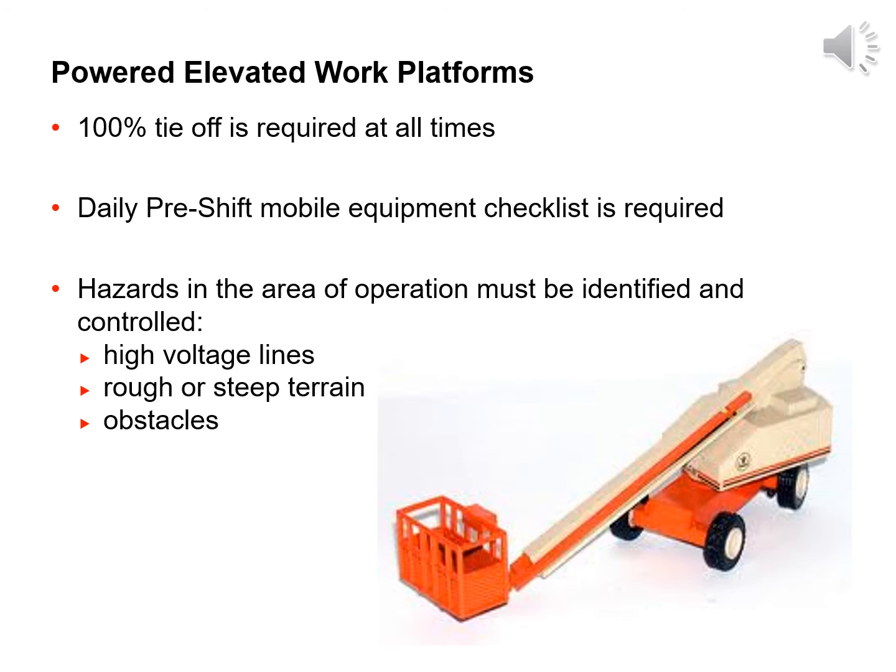You should also remember to maintain safe distances from electrical power lines to avoid electrocution. Drop-offs, floor openings, and other obstacles should also be assessed before operating the equipment. Many accidents have occurred from employees being caught between the man basket and fixed objects, like a structural beam. Used correctly, powered elevated work platforms can be time-saving assets.